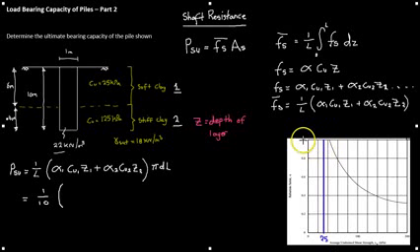It doesn't intersect with the curve, so it defaults as a value of 1 for the reduction factor. So it's 1 times 25 times 6 plus alpha 2. Now alpha 2, we're using 125 kilopascals off this chart, and we should get a value of around 0.43 for the reduction factor. Hopefully you get something similar.